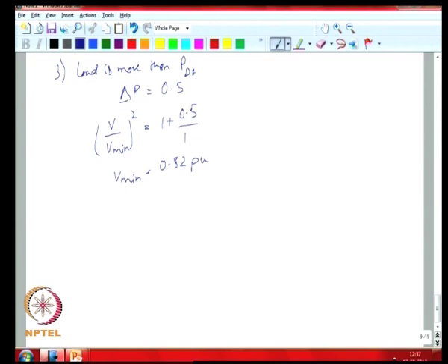So, here you are looking at just the voltage, and based on the voltage you are determining windows, and depending on the mismatch between your DG power and your load power, you could see whether there is a greater chance of forming an unintentional island, or a remote chance of forming one. So, in a case where you have just a few solar panels and your feeder power is in megawatts, then the chance of an unintentional islanding is small, but as the penetration of DG units becomes more, then you have a greater possibility of forming an unintentional island.